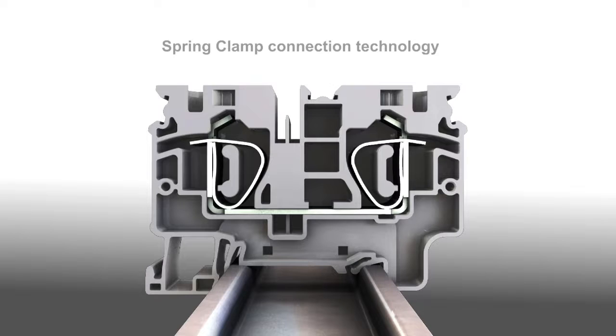And because of the resistance to vibration and shock, because the screw is less prone to open up, those terminal blocks are usually designed in and used mainly in elevator cabinets, in railroad car applications and other machines and vehicles. Clamps are usually made of a stainless steel material to really guarantee that strong connection.